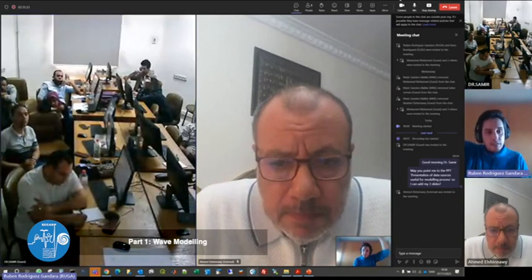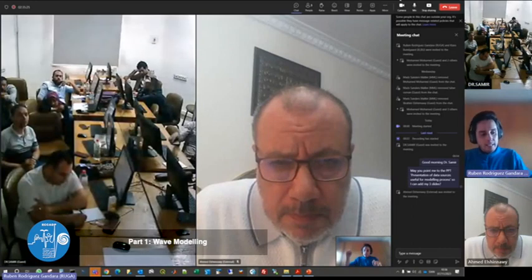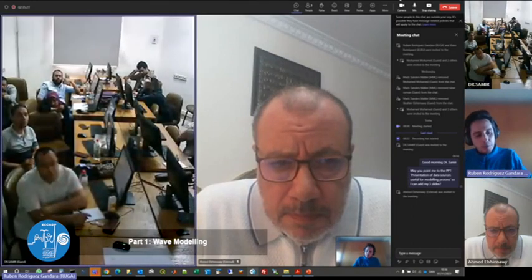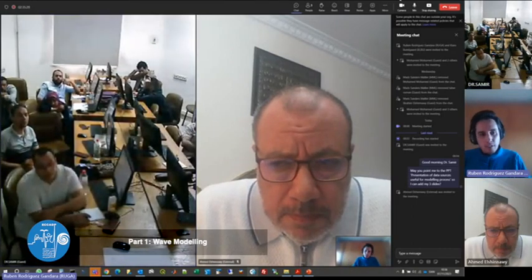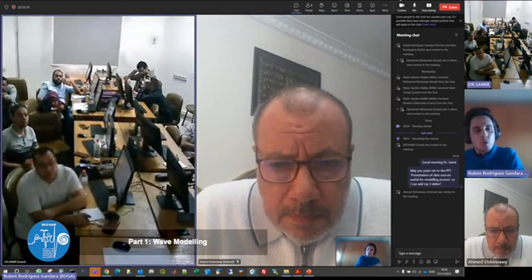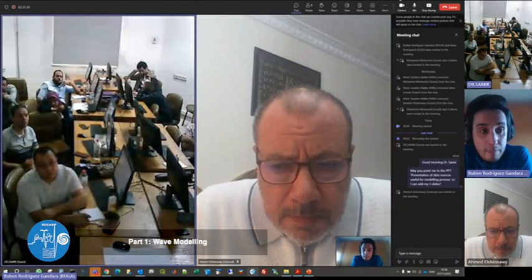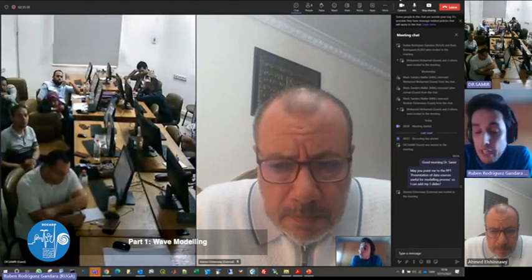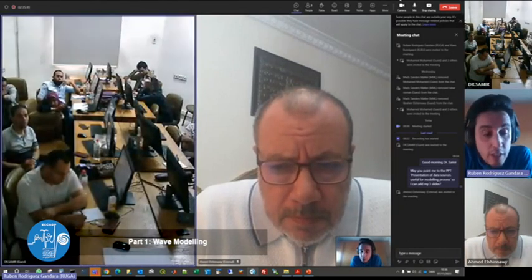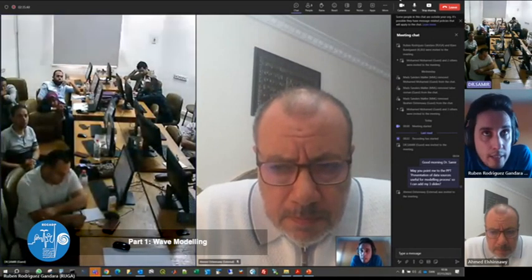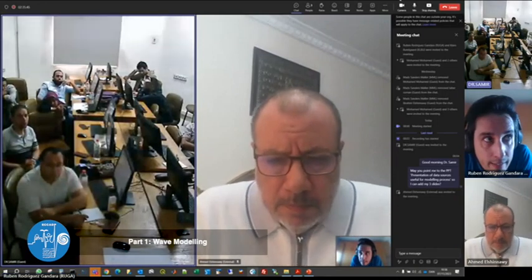It's just the distance from offshore to land. Take the smallest peak period that you're going to simulate, compute the celerity of that wave, and see how long it takes to travel from the boundary to the coast. If it's longer than the update time of the boundary condition, you cannot use quasi-stationary. If it's shorter, you can. Okay. Is this clear? Okay, great. Good.